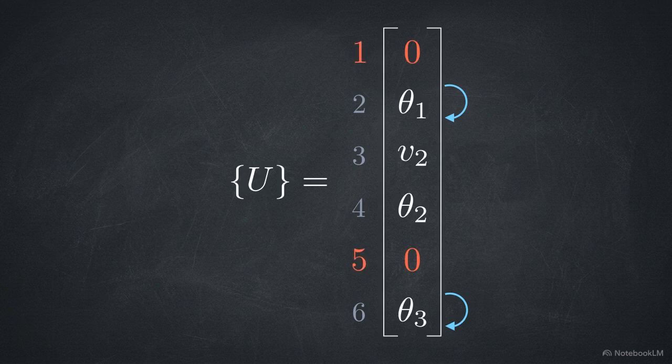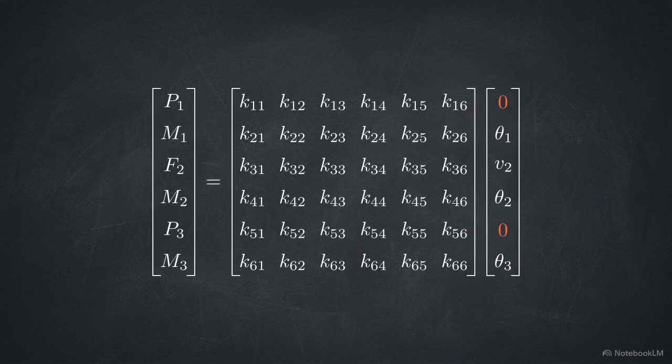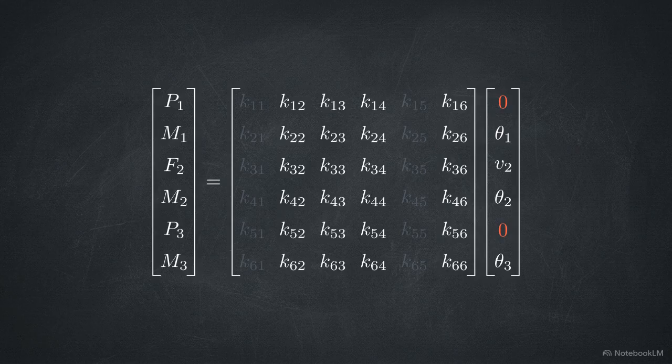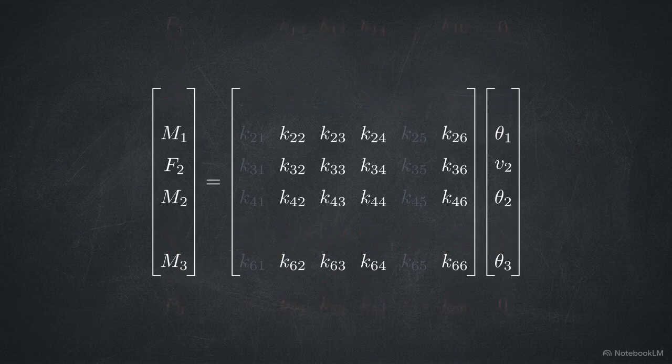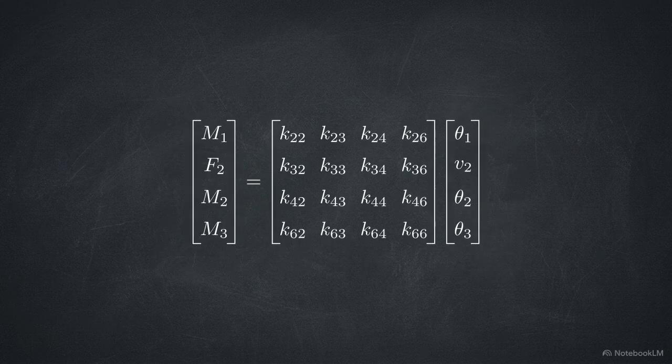We map the indexing constraint by counting down the vector. v1 sits at index 1, and v3 sits at index 5. Applying the 0 multiplication rule to the stiffness matrix using these specific indices, columns 1 and 5 are mathematically neutralized. Notice the primary set isn't a clean split. It is formed by extracting the remaining interior rows, 2, 3, 4, and 6.